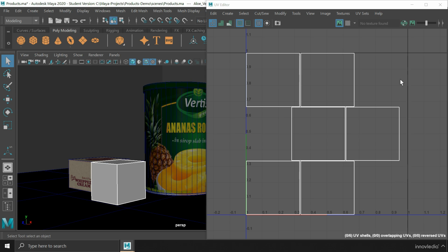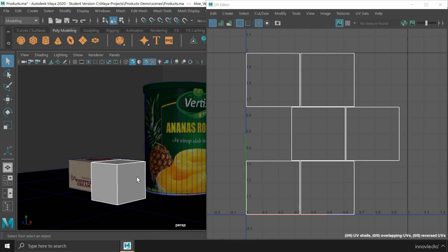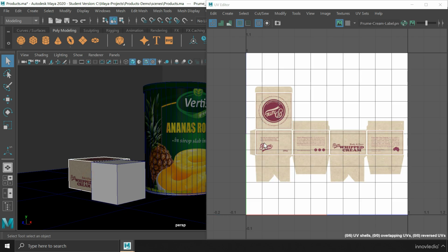Then what we do is we manipulate these projected surfaces to map them on a texture file. And then what Maya does is it uses the same projection to map the texture on the surface of this 3D object. So the projection works in both directions. First, we project the surfaces from a 3D object on a 2D plane, and then we adjust the projection on the texture file as required. And then finally, this same projection is used to wrap this texture around the 3D object. Alright? So, this is how it works.